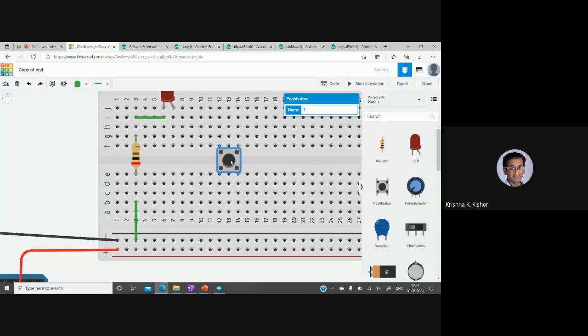One thing that I must tell you, which I recently found out from Satyan sir in the lab, is that you can rotate these components as well. I'll just show it to you. Let's pick a resistor and place it over here, and if you press R, the component rotates. You may not always want to place a component vertically, so you can rotate it. For our purpose, we're not going to do anything like that, so we just keep it like this.